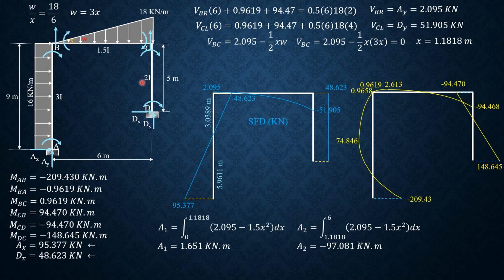This is the left, right, like that, then positive. So that's the approximate elastic curve for the bending moment diagram. As said, it looks like this, positive a little, then negative, concave down, then up. So that's the expected elastic curve.